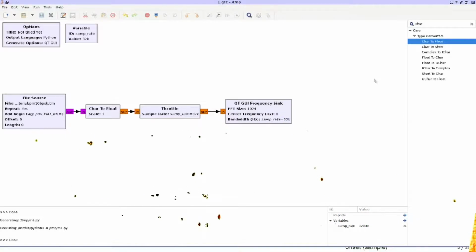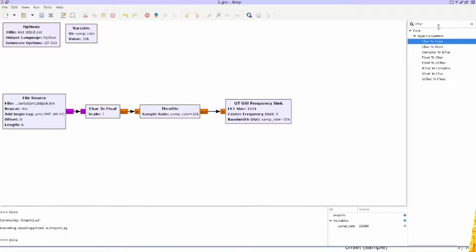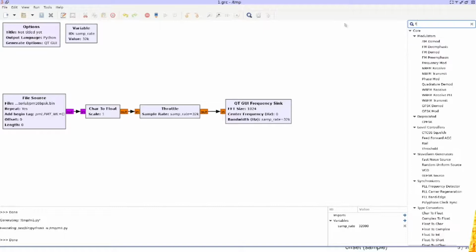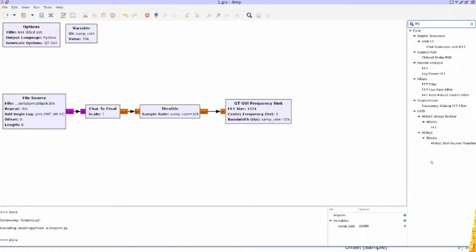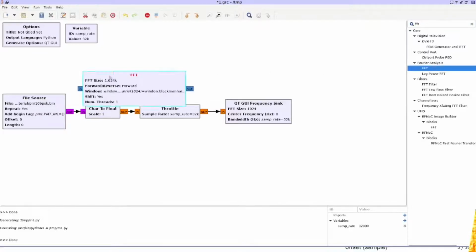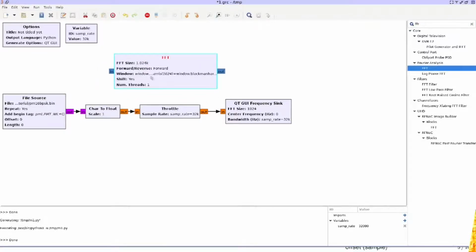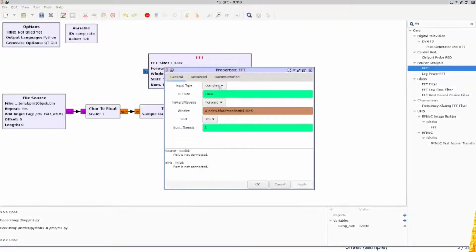So how do we do this? Well, we're going to run this through GNU Radio, and to do this with GNU Radio, we're going to create a Fourier transform, and that's you taking the FFT block here. Now, the FFT block requires that you feed it not with a stream, these are continuous streams, but we need to feed it with a vector.